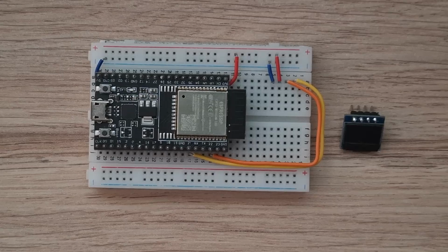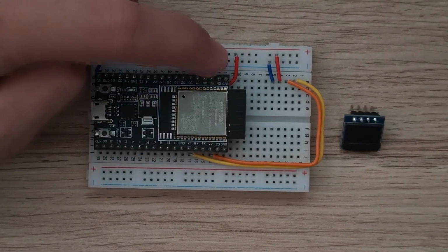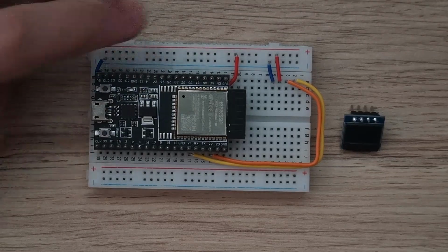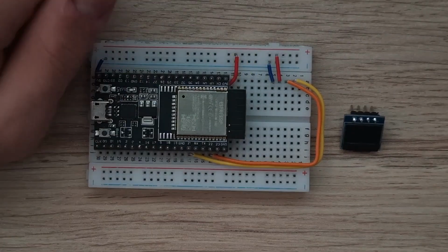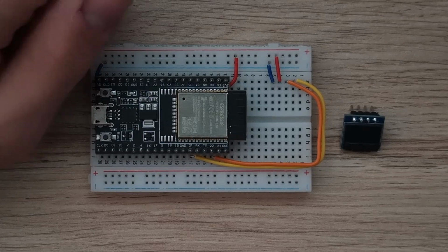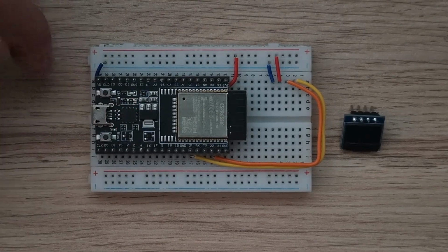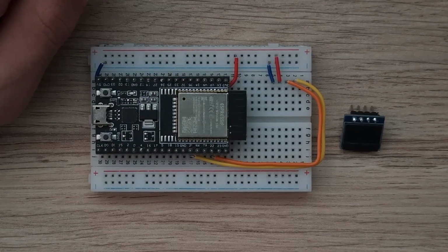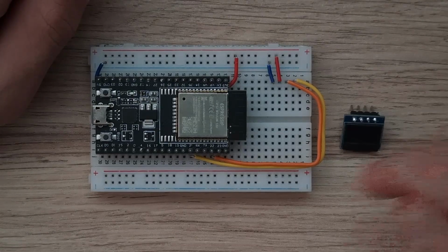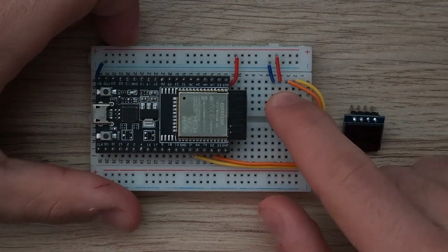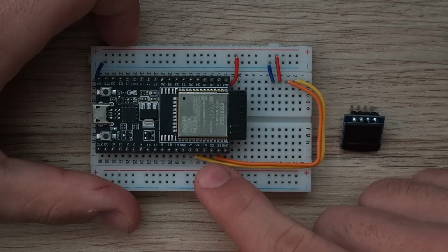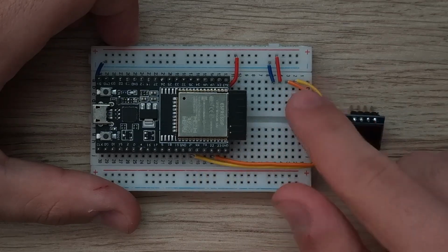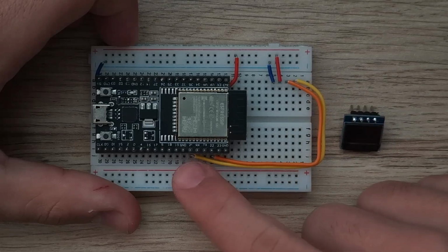Now for the ESP32 I have already connected it, but let me explain. Using these jumper wires here and here, I have connected the power supply to the power line. We have ground going to the first pin from the left, and 5 volts, or in our case 3.3 volts because the ESP works with that, to the second line. Then we need to connect the communication pins, the SDA and SCL. First is the SCL, which is the third pin from the left, which goes to pin 22 on the ESP. Then is the SDA with the yellow wire, which goes to pin 21.